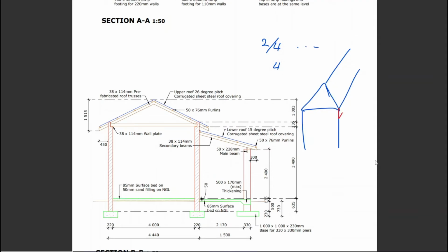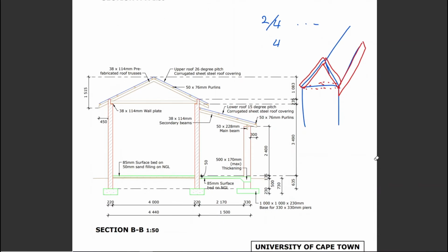Here's your fascia board in red. Since it's running with the building, no factor. If you are doing a barge board, it runs up the slope. You need to apply a factor. If you do not apply a factor, you are basically measuring what's down here, and that is not where it goes in real life. So that is an interesting sort of difference between the two, and this difference carries through to other things.